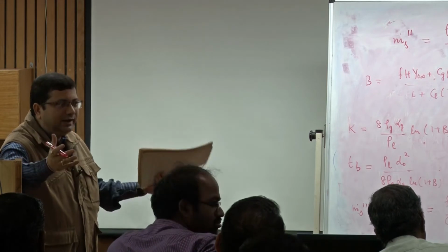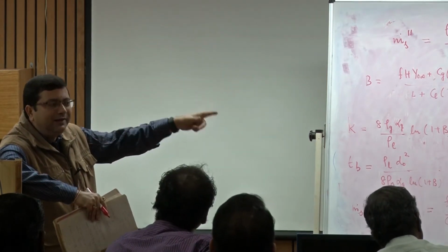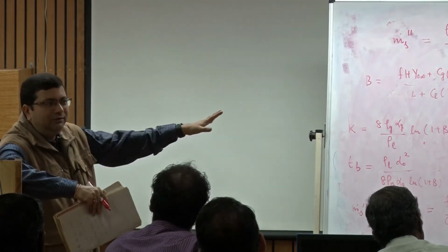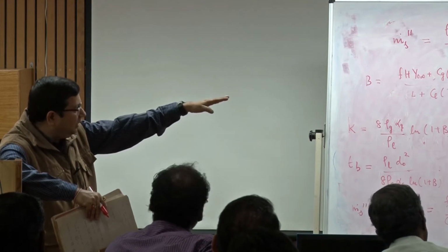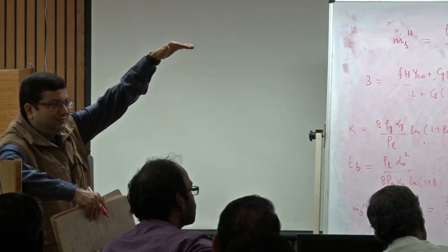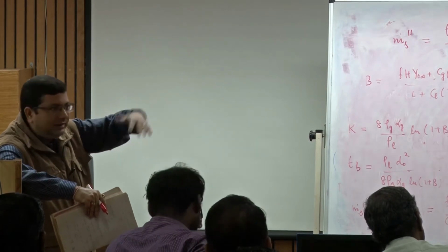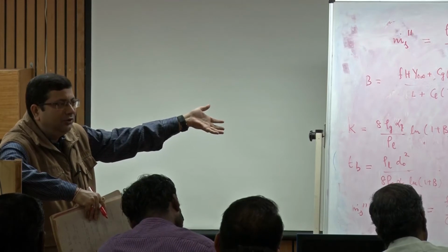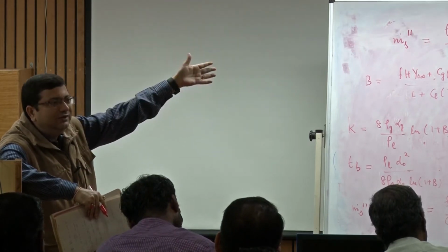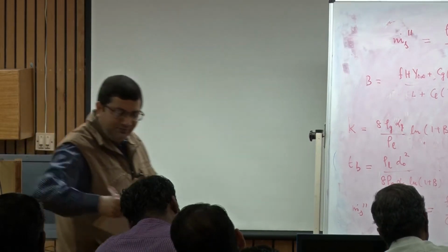They produce much higher energy, because rockets carry their own oxidizer and do not have any other dilutant. So, it is a pure oxidizer concentration. Therefore, Y naught infinity is 1 for rockets, but for everything else, because it is air, 78% is nitrogen, so the oxidizer concentration is low. That is why a rocket has much better efficiency; with a much smaller size we can get much higher power.